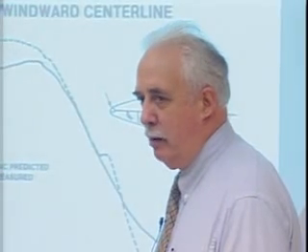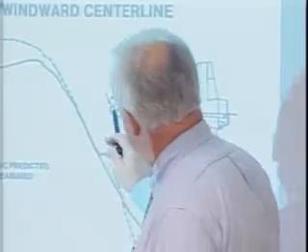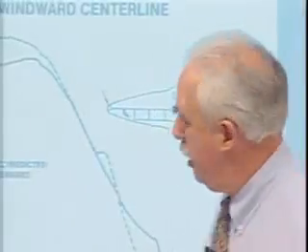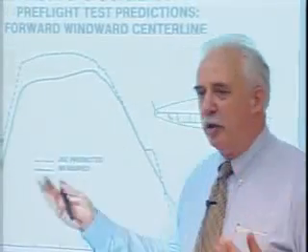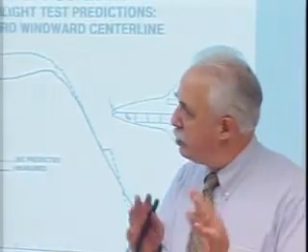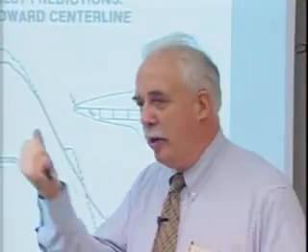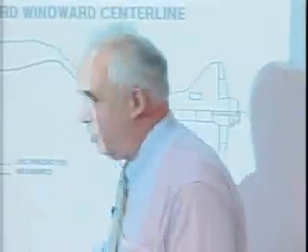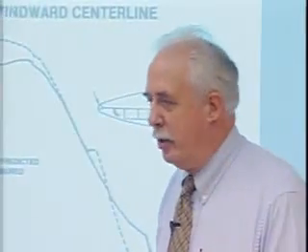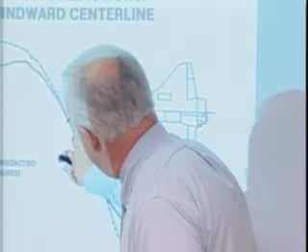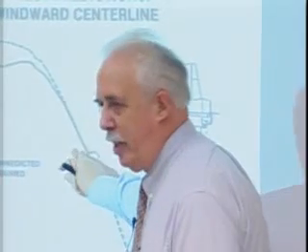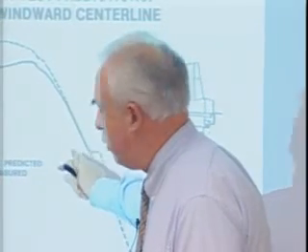What's really going on here? This is right behind the carbon. The carbon is an oven, okay? As the surface temperature of the tile drops, which drops very quickly because it re-radiates, not because it diffuses, we control that, right? It re-radiates. So as soon as the heating drops, the temperature drops. I mean, this is almost identical to reflecting what the heating is. It's dropping like mad. And indeed, we're agreeing quite well. We're kind of out of the real bad chemistry and surface catalysis, which is part of the problem here.